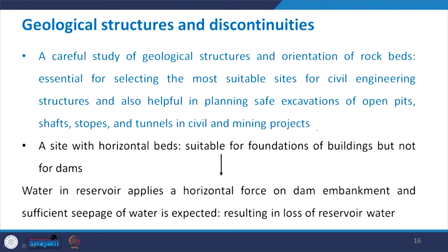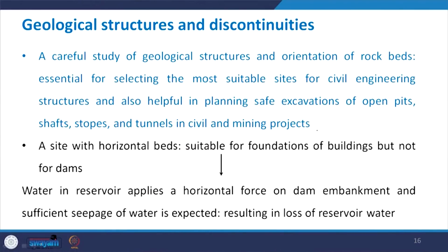The water in the reservoir will apply a horizontal force on the dam embankment, and therefore considerable seepage of water is expected, and once that seepage takes place, there is going to be immense loss of reservoir water, which is not desirable as far as functioning of the dam is concerned. So we say that horizontal bedding planes at a particular site are not suitable for foundation of dams.